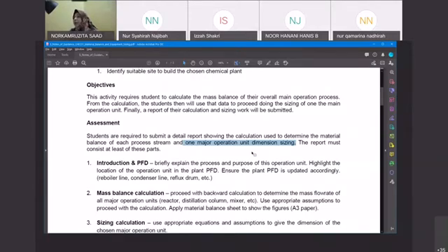So you can calculate the theoretical number of trays that you have, okay? So therefore, if the number of trays that you have is, let's say, 100 trays, which is impossible for a distillation column, okay? It is impossible. So normally you have about 30 trays, okay?